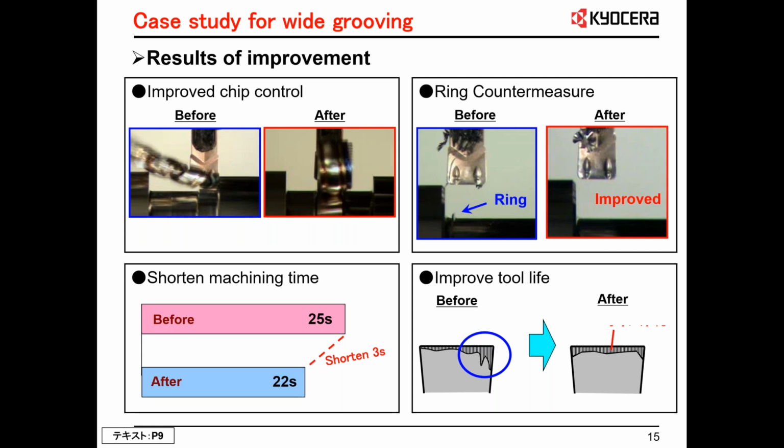It also allows us two things: shorten the cycle time by 3 seconds. More importantly, as you see, when you start doing your plunges simply 1, 2, 3, 4 like this, you're only cutting on one side of the insert. The only time you're cutting on this side of the insert is when you're finishing and walking across the floor.